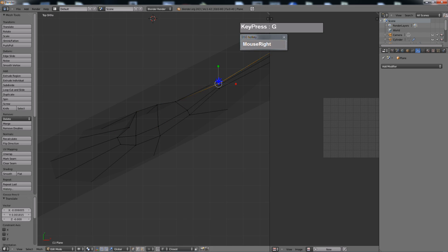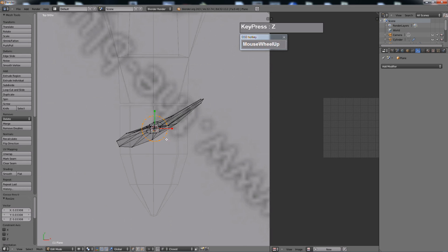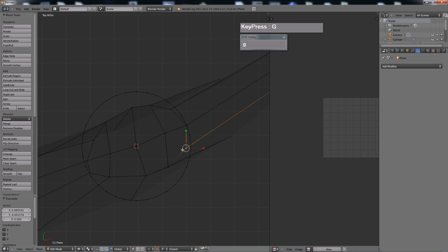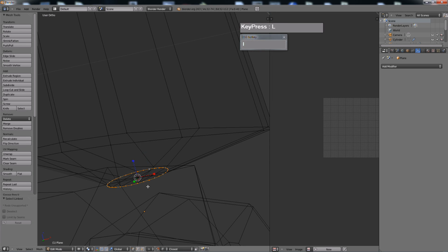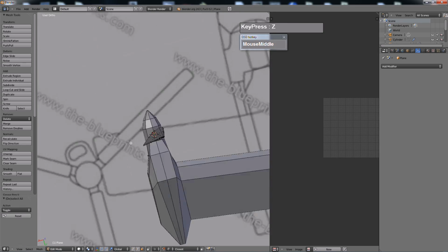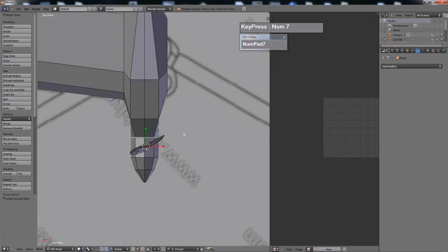So I'm using the clipping command Alt-B to just highlight the section which I want to extrude into a circular section. So what I did was I selected the root frame, and then I just positioned it in the circle, and then I created another circle mesh to be used as a snapping guide. So over here you can see that I'm snapping the root, the ends, to the circular shape. Then I use link select to select the circle and delete it because I don't need it anymore. And now when I extrude, I get a circular root section.